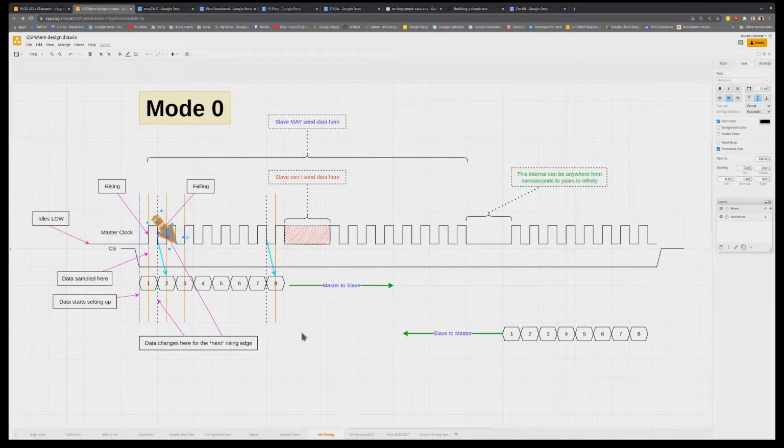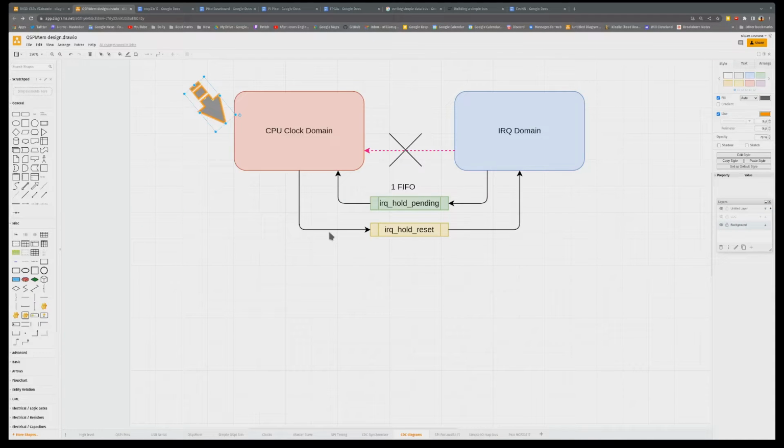That's it. Remember in the previous episode we touched on clock domains where I mistakenly mixed unrelated asynchronous signals? Well, here we are. Let's review it real quick. We had our softcore processor domain right here and our interrupts coming in from some unknown device, or in this case my simulation. I had mistakenly sent the interrupt signal directly to the clock domain or the CPU domain, and that was causing problems.